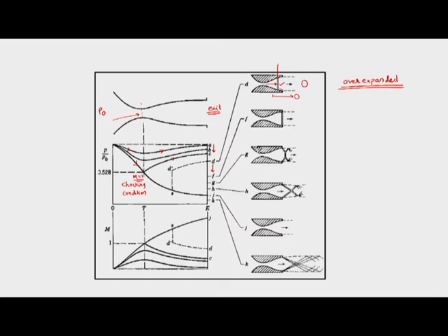So, the shock pattern differs as we decrease the outlet pressure. Initially the normal shock in the duct becomes an oblique shock in the outlet, and then the oblique shock will further reduce its strength as we keep on decreasing the pressure. And for a particular condition, we have the complete supersonic expansion in the convergent as well as divergent nozzle.